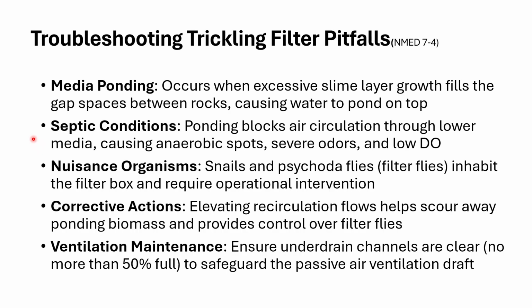Well, if we have ponding, we get the slime layer overgrowing and clogging up the voids, and we have ponding in the lower media, particularly, we're going to have an oxygen deficient or poorly oxygenated environment, and it's going to go septic on us. And you're going to have an odor problem. You're going to have low dissolved oxygen.